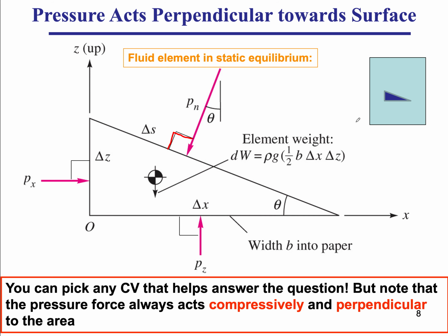And you see, we're not drawing the pressure force from the inside of the object, we're drawing it from the outside, because what we're drawing here, the pressures Px, Pz, and Pn, are the forces of the surrounding fluid on my fluid element that I am looking at over here. So the surrounding fluid acts in a compressive fashion, and the force acts perpendicular to the area.